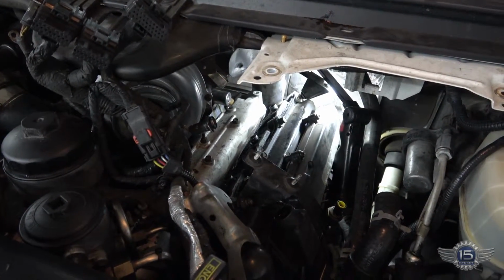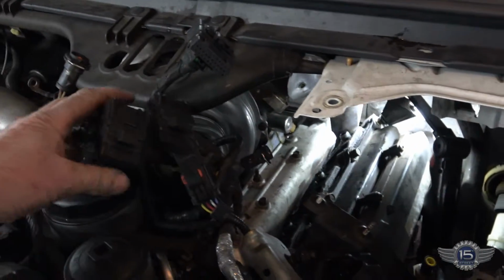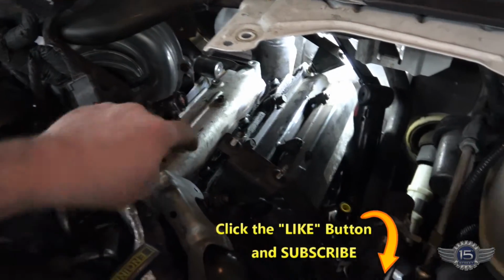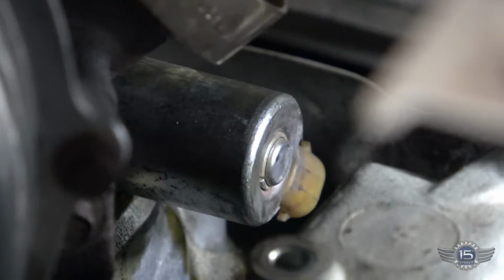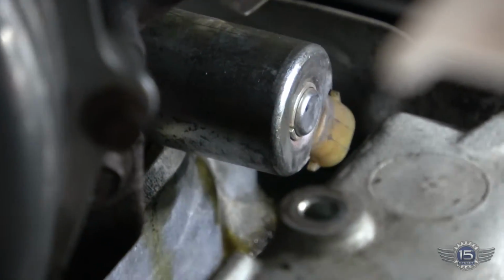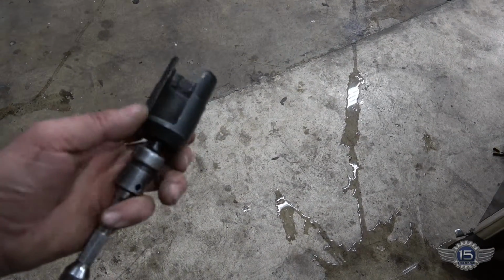Okay, so we got the FICM out of the way, and I took this harness out of the way. This is the harness I took out. This is the FICM connectors, and those are the fuel injector connectors. They mount right in there. So I took those out of the way, and you can see where this regulator is right there, right next to the turbo, right underneath the turbo. So that's what we're going to pull out, and then we'll put that bypass tool in there.